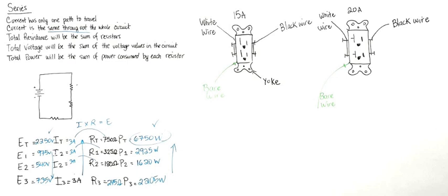And this is where safety as electricians comes in. It's the first thing that we think about as electricians: our safety. What type of tools are we gonna use? All of our tools have to be insulated, and if you're gonna be working with live loads, now they have to be rated.